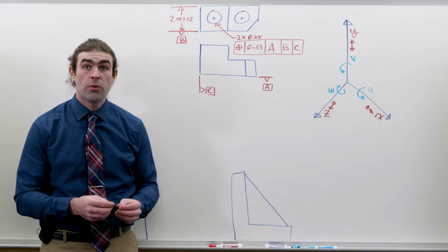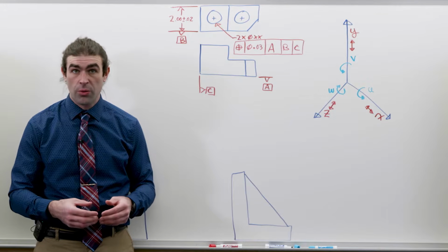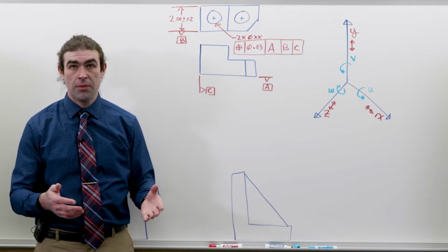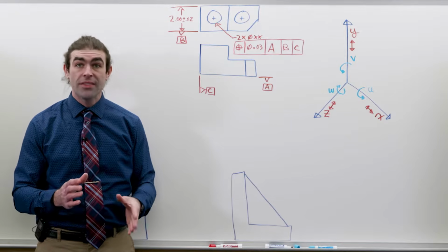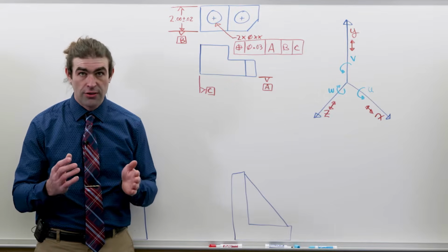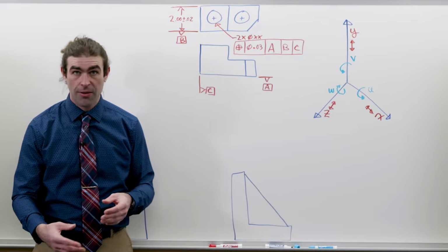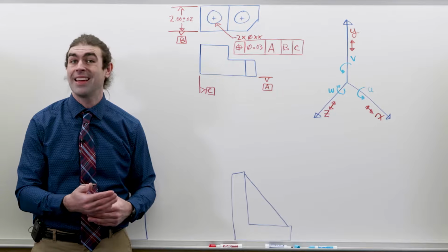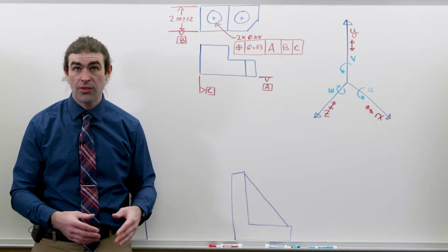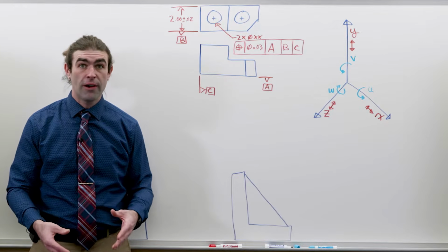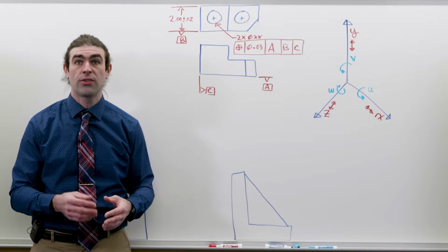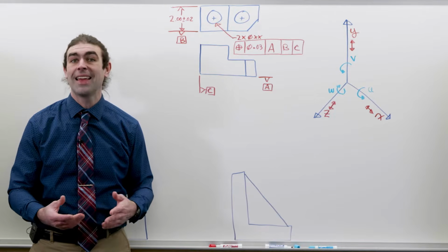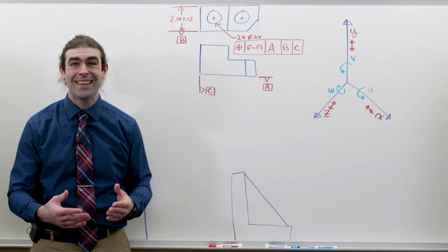One thing I want to mention when we do use the MMC, what it's known as when it's used in the datum reference is MMB, maximum material boundary. You can still check it as if it's RFS. That's totally fine. RFS is always a more stringent call out than MMC. So anything that says MMC, you check it as if it's RFS and it passes, you're good. It's only when the piece fails that you might need to go back and account for the MMC or the MMB.